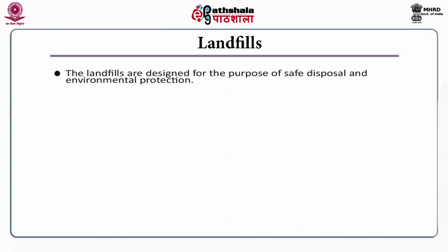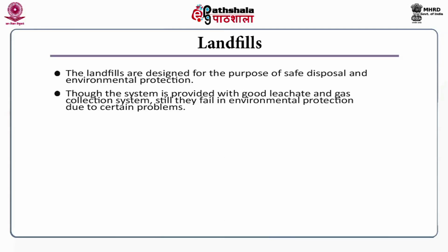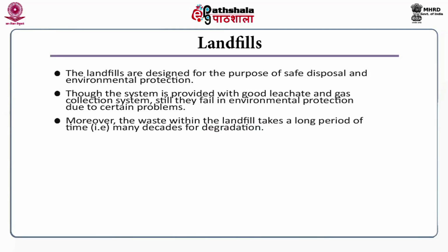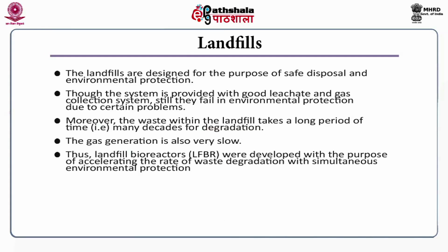Generally, landfills are designed for the purpose of safe disposal and environmental protection. Though you take steps to control the leachate and provide a gas collection system, still they fail and cause environmental damage. Moreover, the rate of waste degradation inside the landfills is very slow. It takes many decades for degradation. Also, the gas generation is very slow. Thus, the concept of landfill bioreactors was developed with the purpose to accelerate the rate of waste degradation with simultaneous environmental protection.